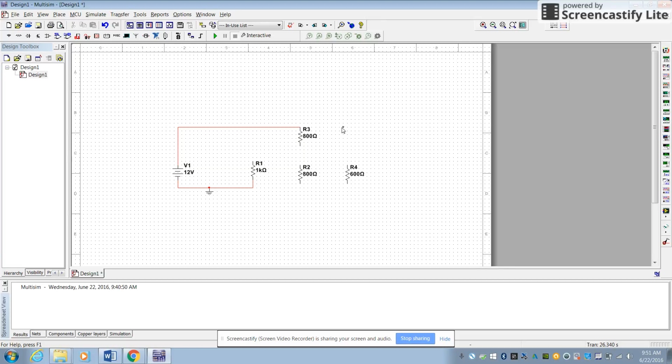It looks like nothing happened, but as soon as you move the mouse, you're going to see a small dot has now appeared under my mouse. Go ahead, take that dot, click it in place, and you now have what's called a junction. This is like a fixed point on your circuit that you can run wires to without running into major issues. You can see I can now drag wires off of that junction, and it's gone away now because I've used it twice. Sometimes when you use it as much as it thinks it'll be used, it goes away.